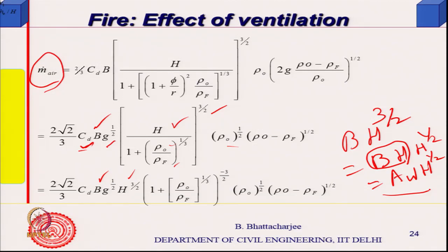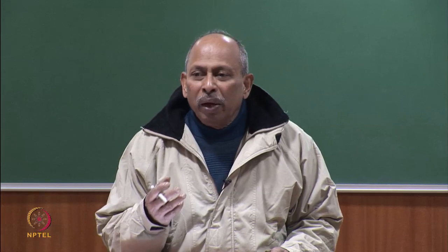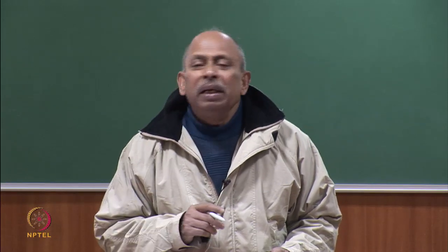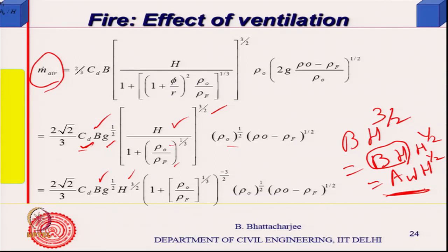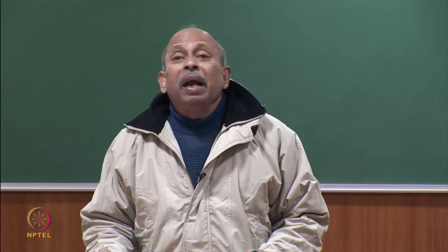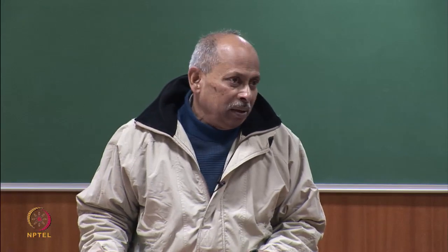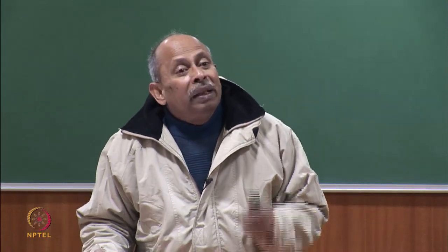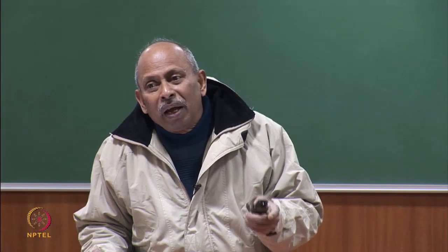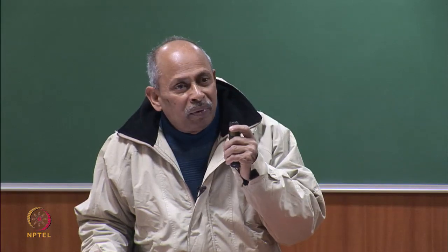Now, remember the ventilation factor I was mentioning earlier, from empirical studies, I gave you a formula for calculating the equivalent fire resistance QF. This factor is called the ventilation factor. The values are not important because a lot of them are empirical, but what I want you to understand is that the total area of the openings multiplied by the square root of the height, which we call the ventilation factor, governs the rate of airflow into the room, right.